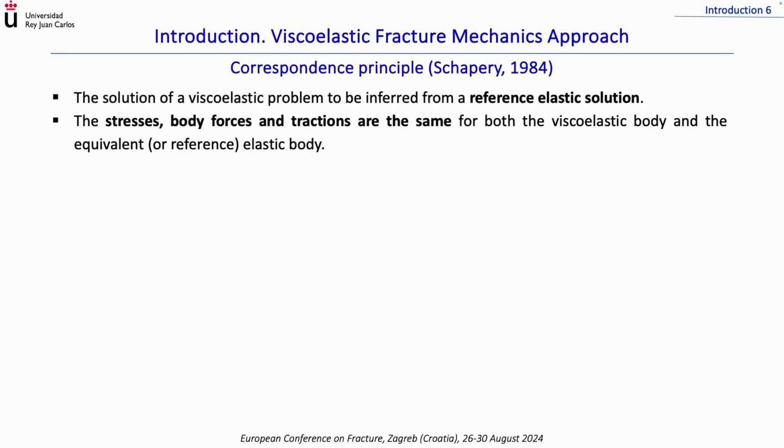As everybody knows, to solve a viscoelastic problem, we normally use the correspondence principle, which basically converts the viscoelastic problem into an elastic one. For the fracture characterization of this material, Schapery in 1984 proposed a particular version of the correspondence principle, making use of a reference elastic body. This principle states that the stresses, the body forces, and the tractions are the same for the viscoelastic material and the reference elastic body.